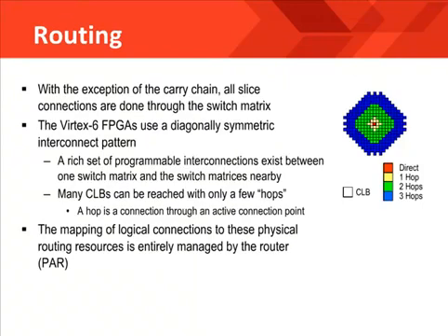The implementation tools select an appropriate routing that may include different kinds of routing resources. The solution that is routed is designed to try and meet your timing needs. To do this, it is important that you add timing constraints with the ISE design suite so you can communicate your timing objectives to the implementation tools. This will allow the software to choose the most intelligent routing solution to meet your needs.